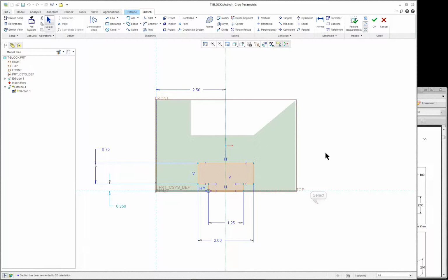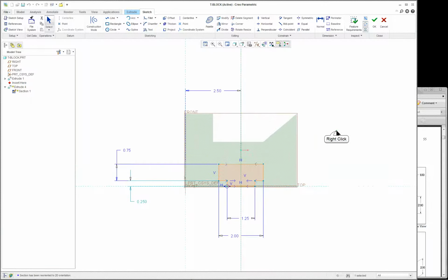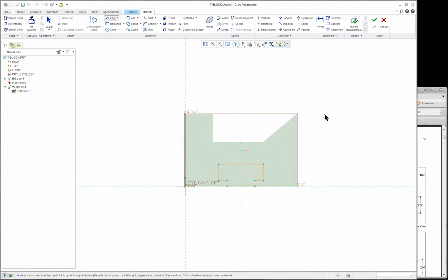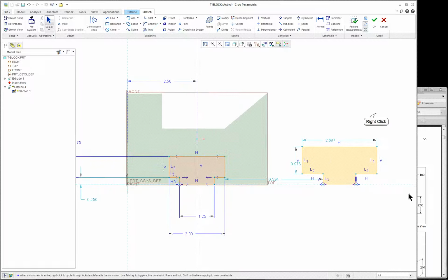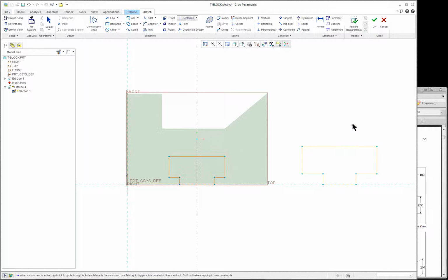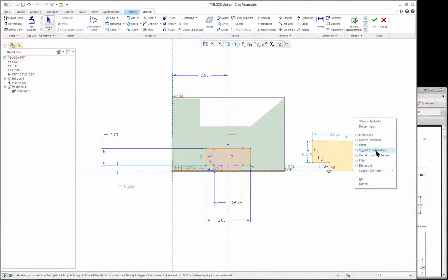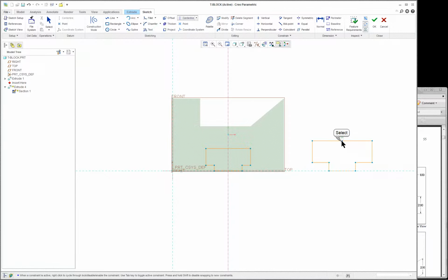And then when you want to start sketching, line chain. So for instance, I'll do it in here. You're going to notice I don't have a center line. Like so. But I could have put center line in first, might have been a good idea. And here's another thing. ProEngineer changed, or I should say, I'm sorry, Creo changed the name from center line to construction center line after the book was written.